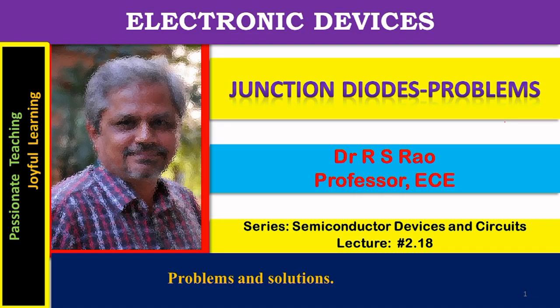Electronic devices, junction diodes, problems, series on semiconductor devices and circuits, lecture number 2.18. PN junction diodes are semiconductor devices, two-terminal devices. These are non-linear and unilateral, well known for their rectifying properties. They offer high resistance to current when it is in one direction and offer very low resistance when the current is in the opposite direction.